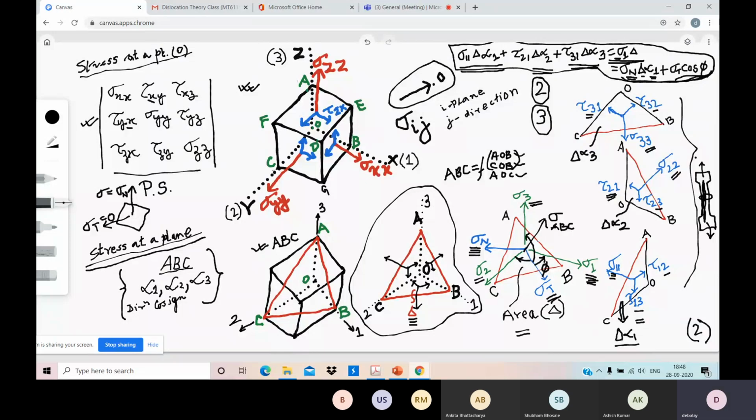So here I will write that there is one normal stress on the perpendicular cross-sectional plane that I write as principal stress in Roman. Principal stress is written in Roman, sigma Roman 1. Sigma numerical 1 is the net stress acting along direction 1. Sigma 1 is the stress tensor component acting on plane 1 along the direction 1.